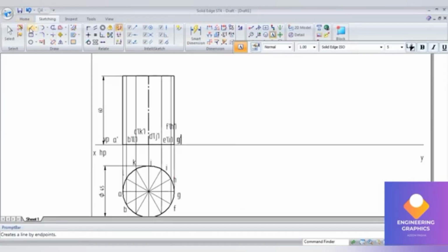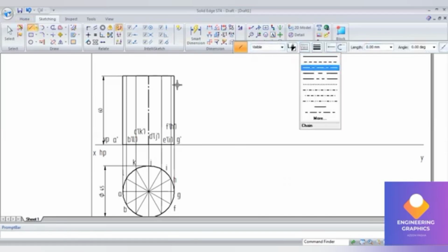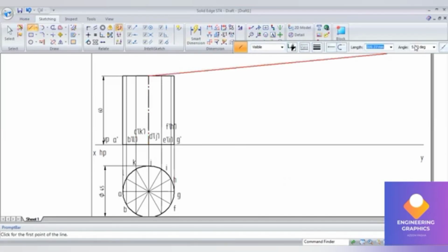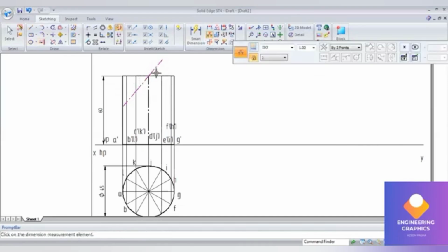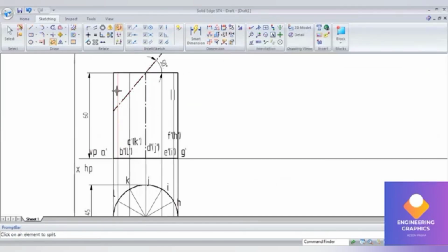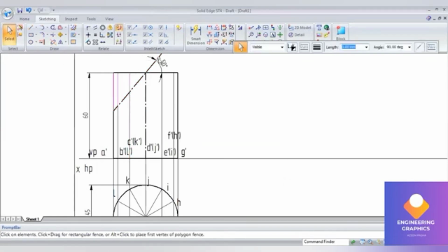Now draw a section plane by taking the top face center and giving an angle of 50 degree. And then extend to next, I'll be extending downward here. So you can see that the upper part I'll make thin by using the split command here, with 0.13 mm thickness.